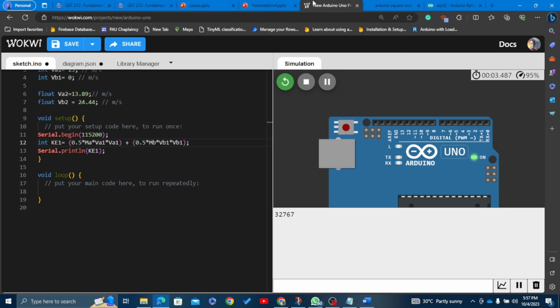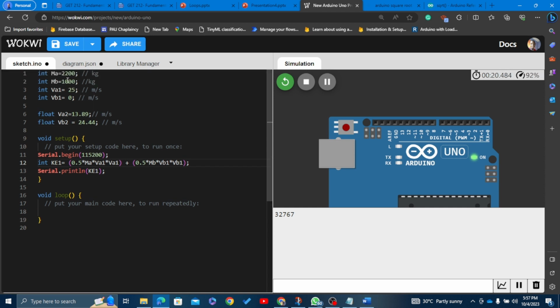Why? When solving maths while programming or in Arduino, it's best to use float, because you don't know how the numbers are going to change throughout the whole solving process. For example, now I use float values here, and I'm using them to get integer values. That's not really a good idea, because now they're all going to be treated as integers. So during the whole process of solving, it's probably going to cut out all the decimal part, because the variable is an integer value.